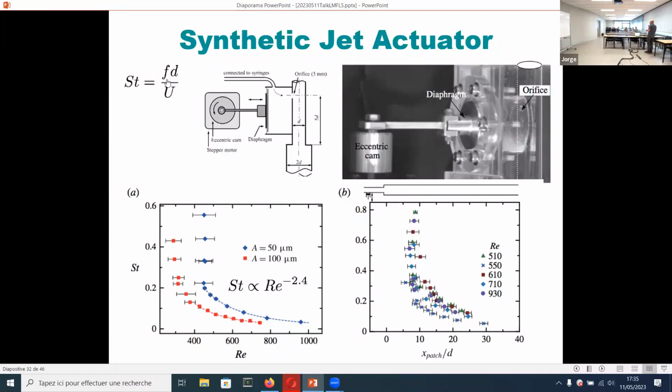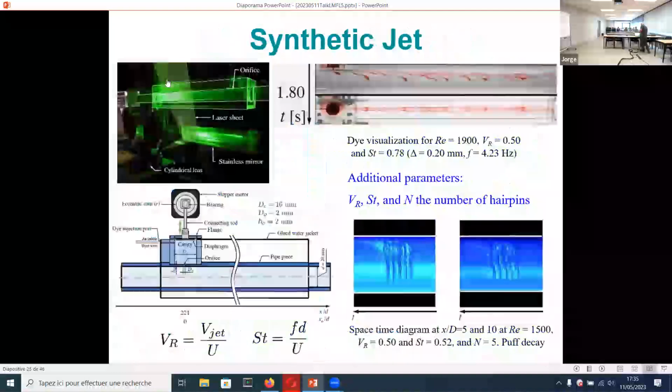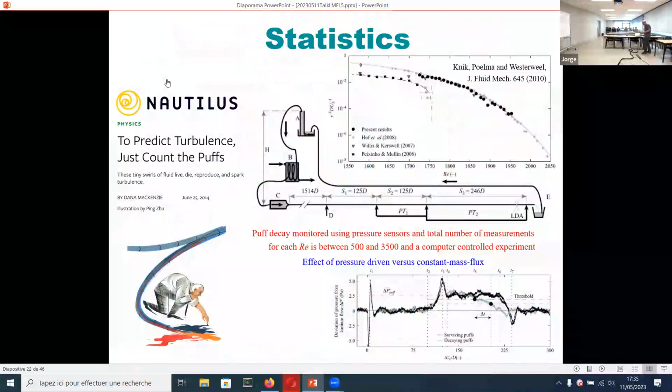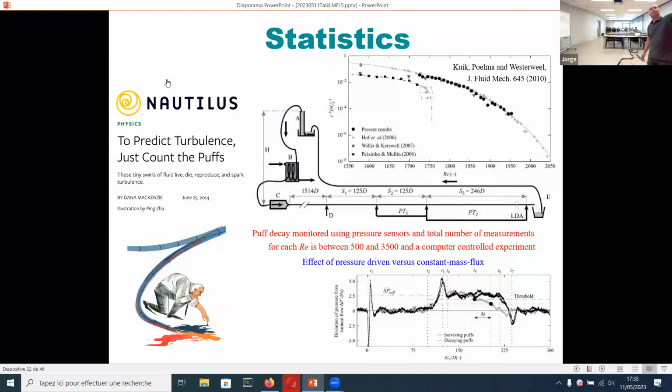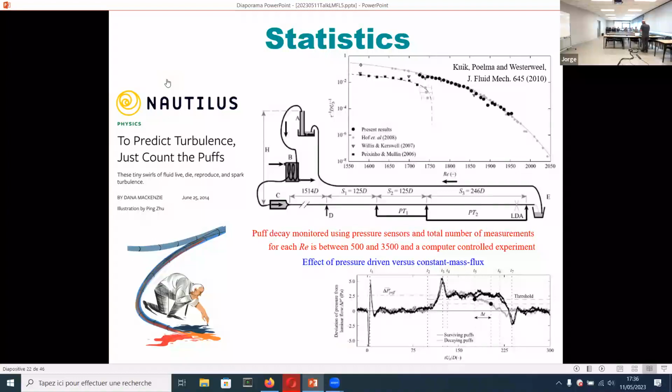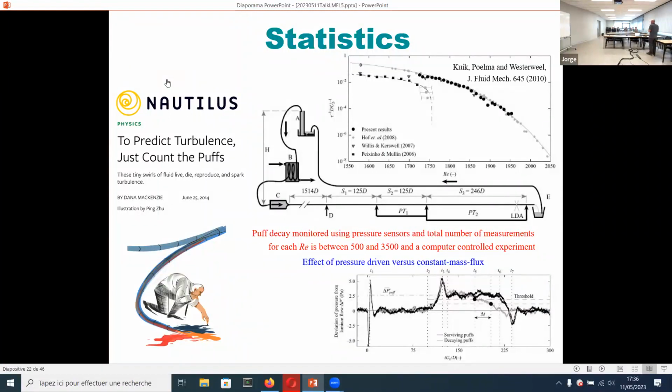Of course, when you introduce a disturbance, the flow is incompressible. So it is clear from the picture here on the experiments in Delft. Once you introduce the disturbance, the whole pipe, the whole flow, all the molecules in the system will know it. That's maybe one of the advantages of the synthetic jet, that you can progressively increase. There's no abrupt spike, but I don't know about acoustic actuators.